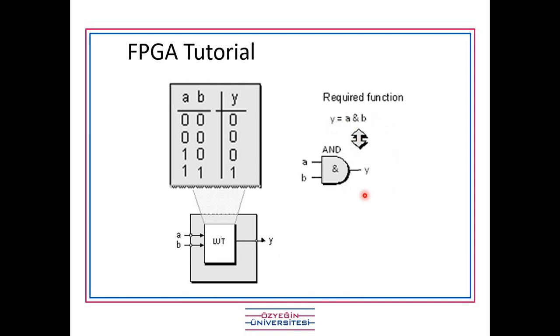The synthesizer will convert them into LUT blocks. It could use a lot of LUT blocks and gives us the output according to the description that's given in our code. And the LUT blocks that we have mostly have 2 inputs and 1 output. Sometimes they have 3 inputs and 1 output. The most I heard so far is like 4 inputs and 1 output. So if I have 16 inputs and 1 output, I have to use a combination of like 2 LUTs or 3 LUTs, 4 LUTs, something like that. I have to combine all of them. Okay.